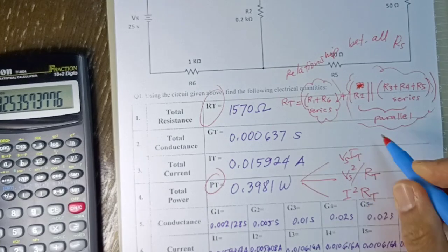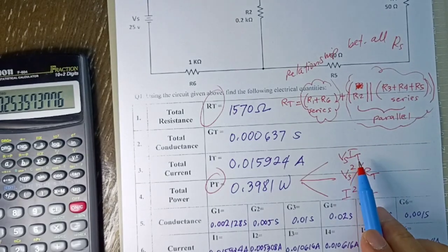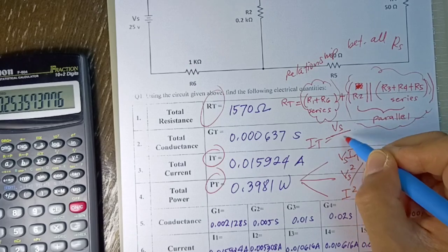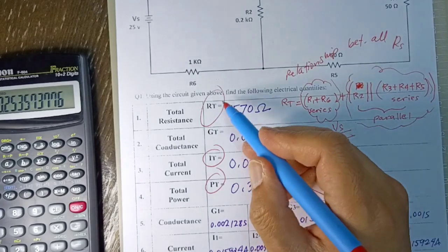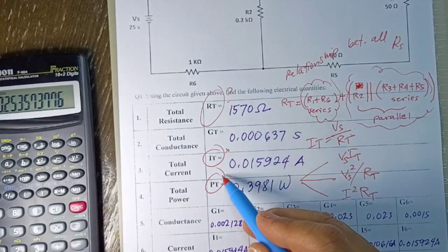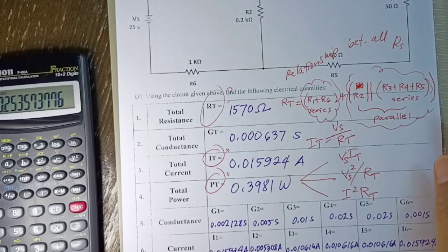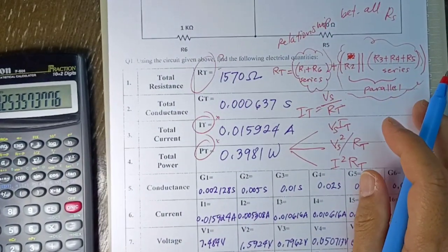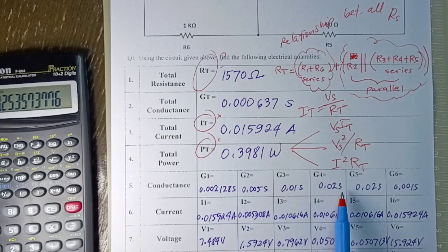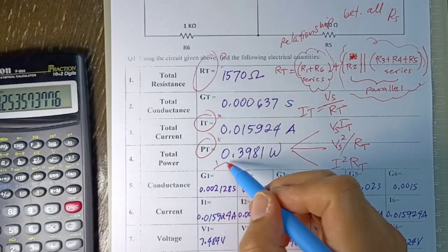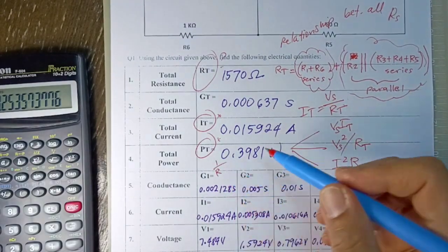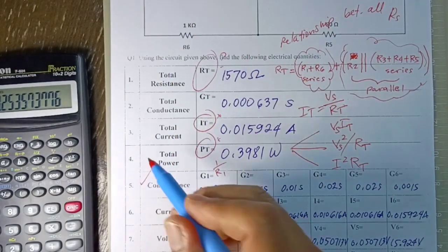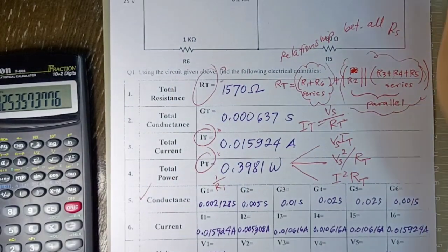Now, you may say that if you use the I total or the current here, it will not be wrong. But remember, the I total is equal to the voltage source divided by the R total. So again, if your R total is wrong, this will be wrong. Now, maybe you will be right with the other values like G1, G2, G3, G4, G5, G6 because this is only 1 over R, 1 over R1 plus 1 over R2. So it's easy because the resistors are all given. Maybe here you will not have a problem.